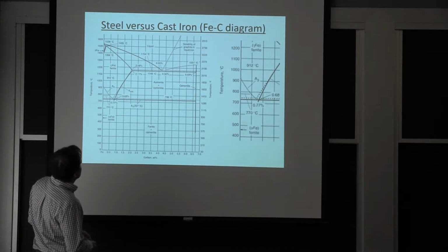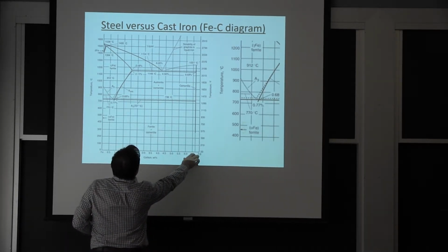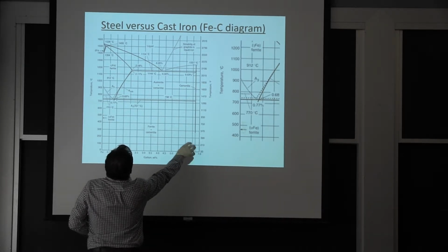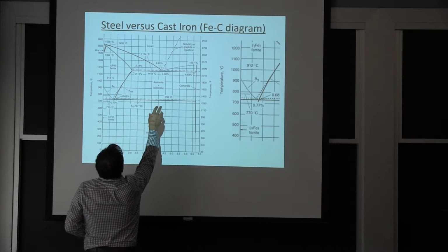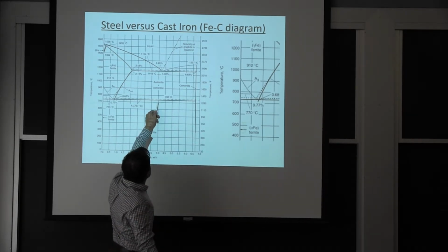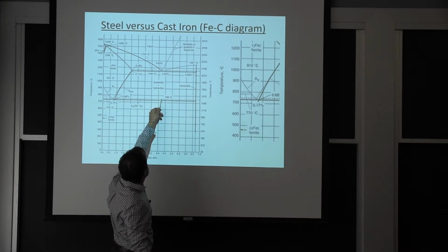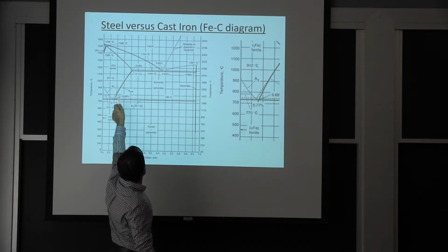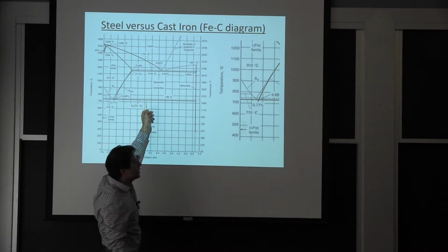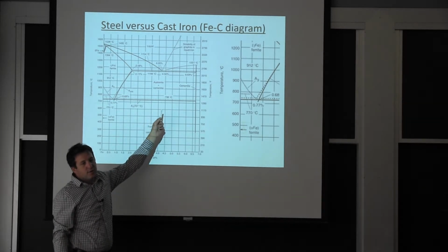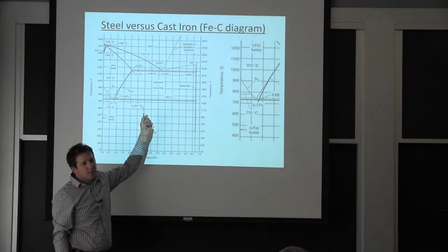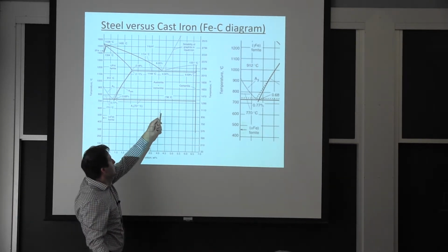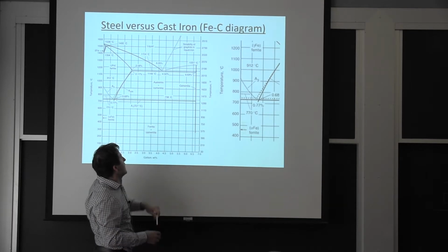So that's a very hard particle, an intermetallic, if you will, here. And what happens is you've got these two regions where you can have some transformation. The lowest temperature liquid is the cast iron here, and that will give you the eutectic transformation back into austenite and cementite, and there are a lot of different cast irons. I'm only giving you a brief overview to say we use them, and we can make them ductile. I've shown an example of that, but we didn't emphasize this portion of the diagram too much.